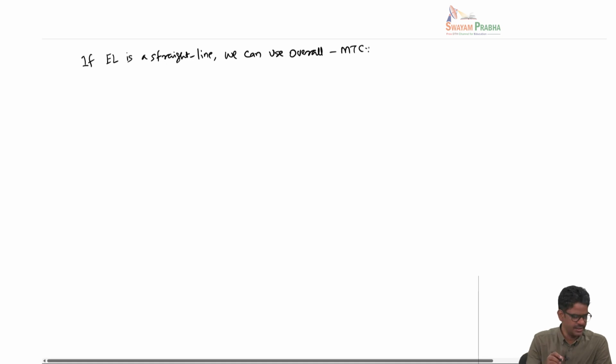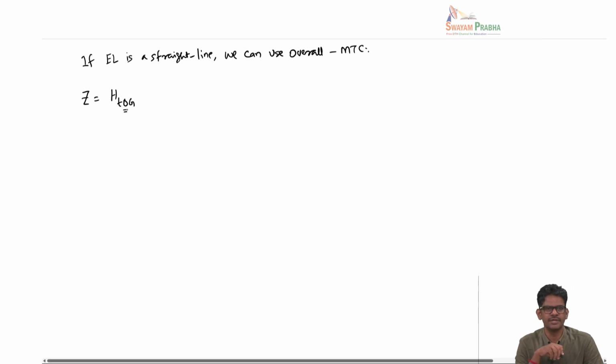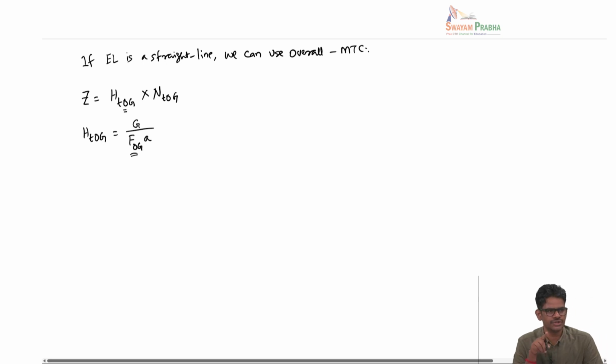So then you can write a set of equations. So now I am introducing this O here to denote it as an overall coefficient. So here you can see this mass transfer coefficient FOG is the overall gas phase mass transfer coefficient.